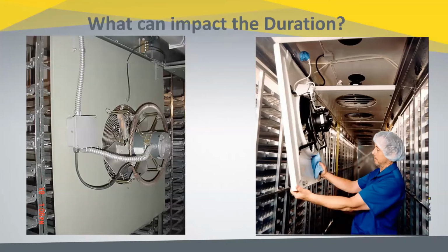You also see the picture there on the left where this particular fan board has the heating element mounted right on the motor. And so this particular machine has had the ducts removed. It's better heating, more uniform, and this machine probably has a split cooling upgrade in it as well. So we recognize that a couple of upgrades being installed really promoted some uniformity, or will promote uniformity in the machine and help impact that duration.